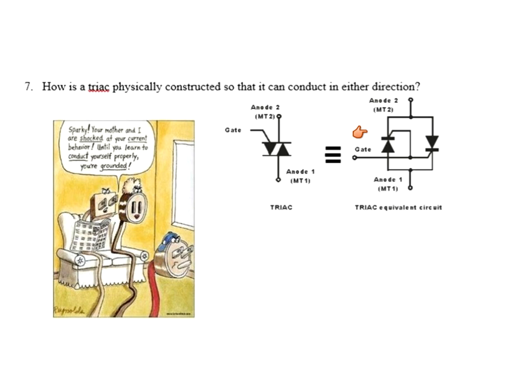As a matter of fact, just for your information, it's very, very popular for really high power applications to use two SCRs back to back acting as a triac. So when you see that in a control cabinet, the reason they do that is it can handle a lot more power in two packages than a single package. When you put two SCRs together in one package like that, one package has to handle all of the heat. But if I keep them separate, it can handle a lot more heat and a lot more power. So typically triacs by themselves will not handle as much power as an SCR package, but you will see SCRs placed in parallel back to back to replace a triac. So that's how it's constructed.